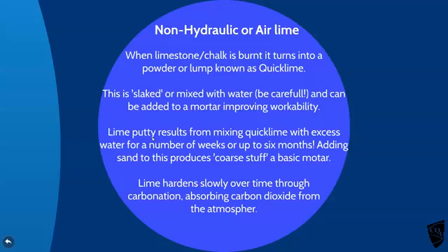Eventually, when it becomes saturated with water, you end up with a putty, and that can be used directly for pointing, but again, it's not good on the hands. You normally allow the putty to mature, like a good beer, so they'll give you up to 6 months sometimes. Add a little bit of sand to it, which gives you a basic mortar.